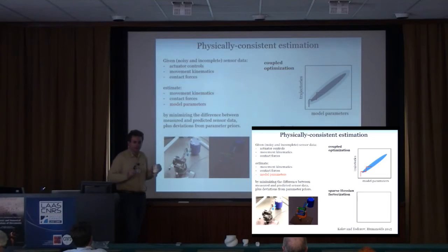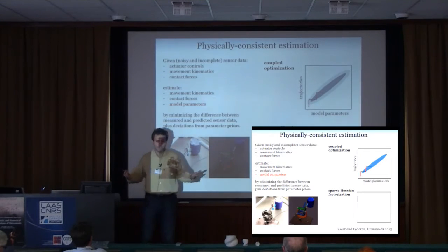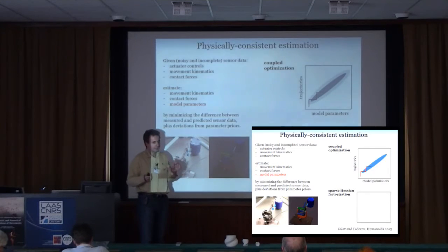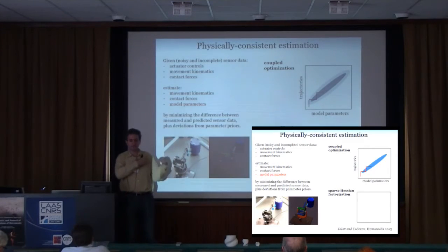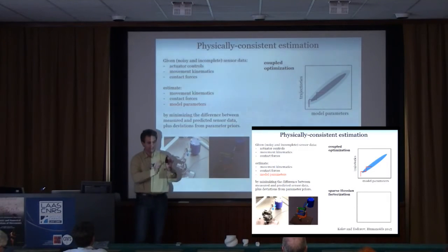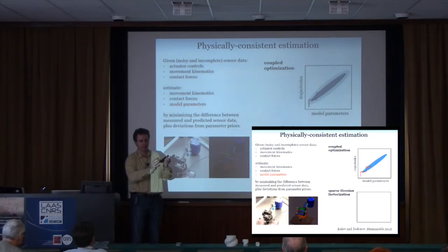Now, you might have thought that you can collect a bunch of data, fix it, and pretend that you know what the real trajectories of the system were, and then do inverse dynamics or whatever, do system ID on it. And in general, yes, for simple systems like a fixed base actuator that just moves around, that's okay. When you have contacts, the problem is that suppose your trajectory estimator data processing made an error of even 1 millimeter.